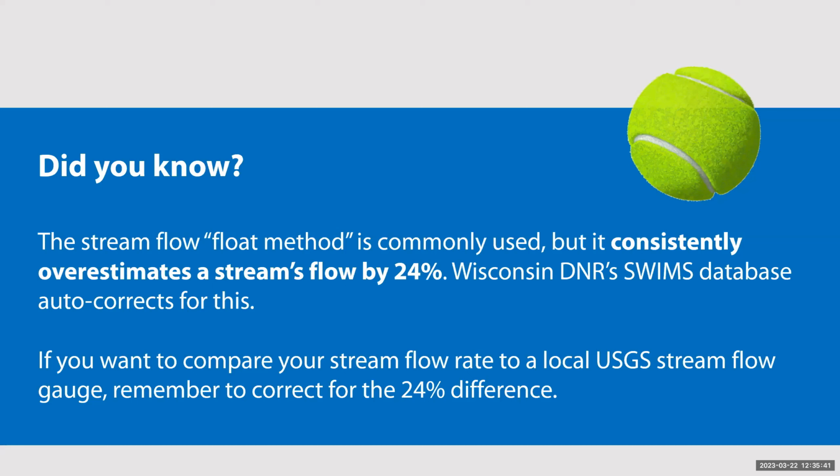So thank you. So we tell volunteers, if you have a stream gauge near your stream site and you're doing the stream flow float method that we teach, compare it to the stream gauge, make sure you're correcting for that 24%.